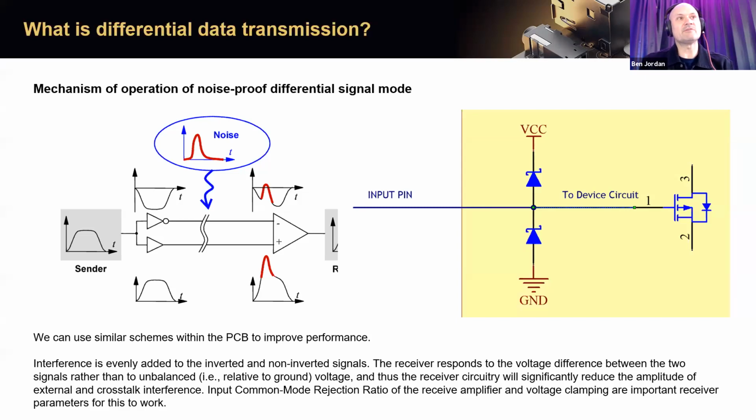And similarly, if you have a negative going pulse, if there's added noise or an excessive voltage ringing on that negative going pulse, the clamp diode to ground will short from the ground of the chip minus 0.5 volts or thereabouts, the forward voltage drop of the Schottky diode.